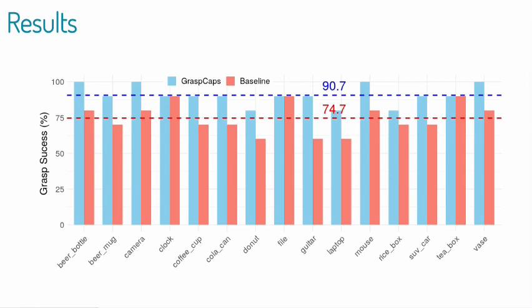We observed that most of the failures were mainly due to predicting the grasp point near the edge of an object. As the gripper initiated the closing motion, the object's position could be affected, leading to potential displacement.